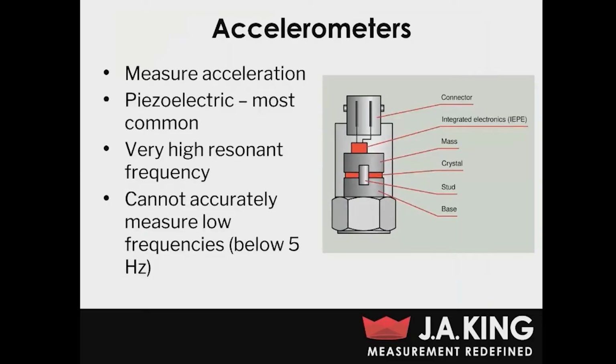So now, how do we actually measure and control our acceleration during testing? The way we do that is with accelerometers. And the most common type of accelerometer, the one that we tend to use all the time, is piezoelectric accelerometers. And you can see I've put a figure here showing the basic makeup of how these accelerometers work. And essentially, it's just a mass and spring system, with the spring actually being a crystal. And as that crystal compresses or elongates, it's going to generate an electrical charge, which is then converted back to acceleration by your vibration controller.